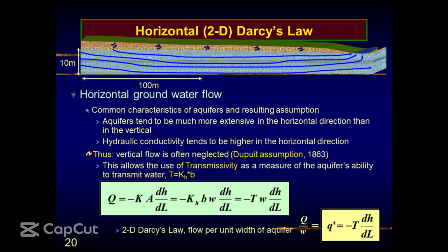Partially penetrating well. Is it horizontal or vertical? Some will be horizontal, some will be vertical. Can you see that? Are you following? Okay, so this is the flow pattern. When you have a partially penetrating well, around the vicinity of the bottom of the well, the flow is not purely horizontal. You have a lot of vertical components of the flow in that case.